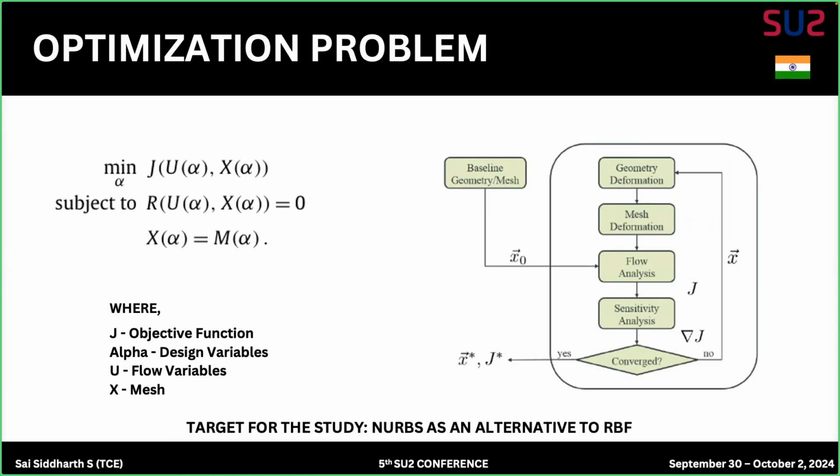An optimization problem can also include multiple objective functions, as we know, such as minimizing the drag while conserving lift. Geometrical constraints can be introduced without significantly increasing the computational time, such as maintaining maximum airfoil thickness and ensuring wing volume does not decrease as well.